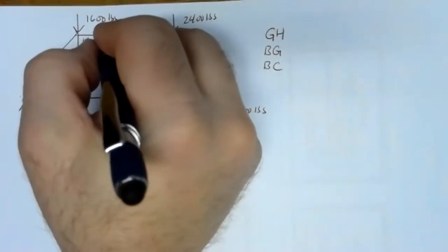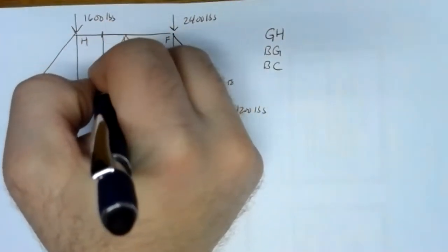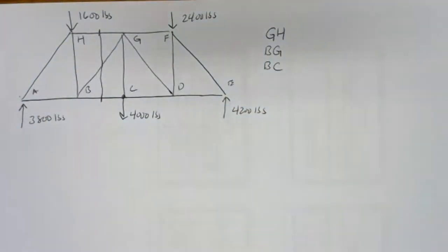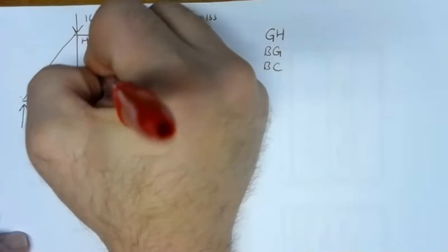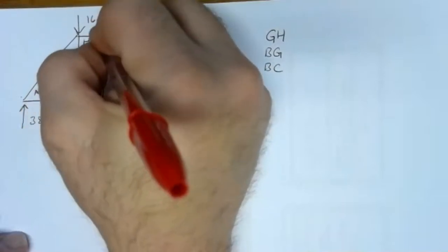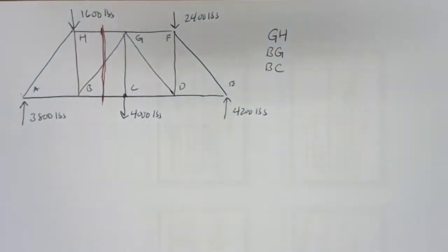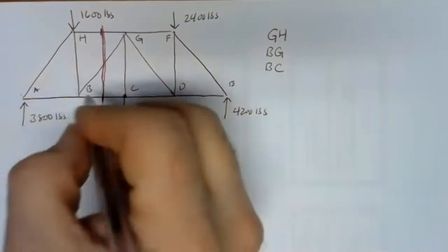And that's how we determine our cutting plane, or our cutting surface. So the cutting surface is a tool. It's really a part of the system boundary. And I'm going to draw that in a slightly different color here to try to draw that out a little bit. So that's our cutting plane. Now the cutting plane, or the cutting surface, divides the inside from the outside, essentially. It's where we're trying to expose our unknown forces. It's really part of the system boundary, and system boundaries have to be closed.